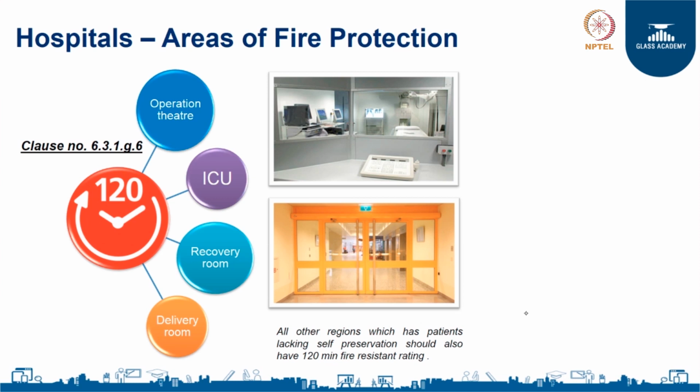If you see all these rooms, these are places where you cannot interrupt the activity or the operation that is happening inside that place. So, you need to ensure that whatsoever happens, the fire does not come into these areas of occupancies for at least a period of 2 hours.